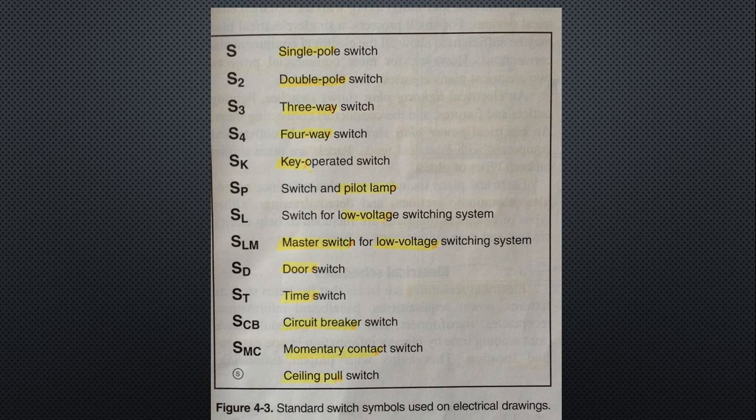Wiring symbols. Electrical plans do not show the exact location of conduit runs. However, conductors that connect devices are shown as irregular arcs. These arcs are dashed when the conductors are concealed in the floor and solid when the conductors are in the ceiling or walls.